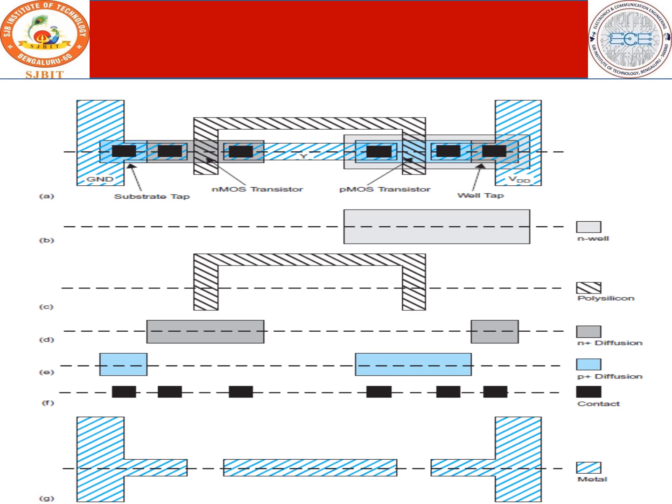Next is contacts. Wherever you require contacts, this is where you require contacts. So contacts are here. Rest all, no contacts. And finally your metal, which is helping us to pull out the leads. So this is where your polysilicon is coming out, and different terminals like source, drain and gate with the help of VDD and VSS. So this is how the different maskings are represented.